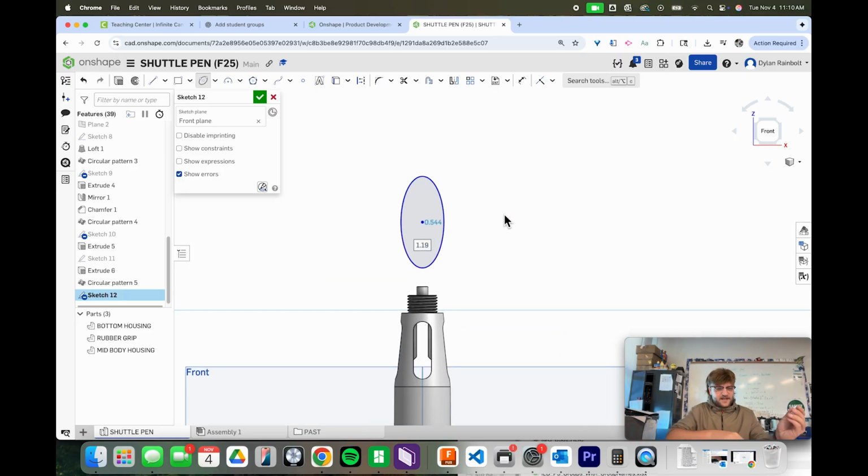Now, what I'm going to do is get these measurements using the dial caliper. And since it's been a little bit of time, I'm going to make sure that this is calibrated here, all good to go. And so it's all calibrated. I'm going to go ahead and tighten that screw down there. Also, of course, we wanted to make sure that this guy was loosened. And so what I'm going to do is get the major axis here of this ellipse.